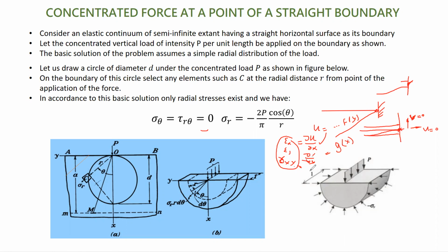Substitute u and v in the third equation, and you get a relationship between f of x and f of y, and that expression for every value of x and y should be equal to 0, from which you should be able to calculate the functions f of x and f of y. And at the end, you end up with the equations for the displacement, which has at least 3 constants. Constants, not a function of a variable, 3 constants. This is as far as the integration of displacement goes.